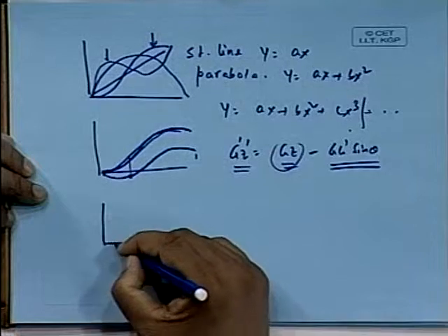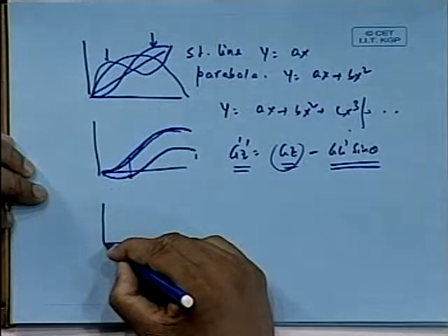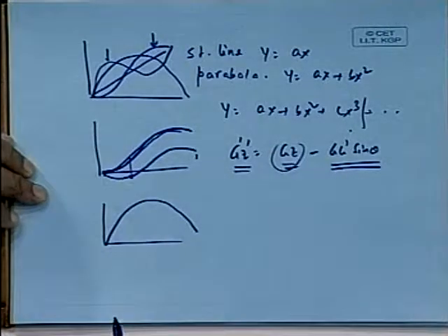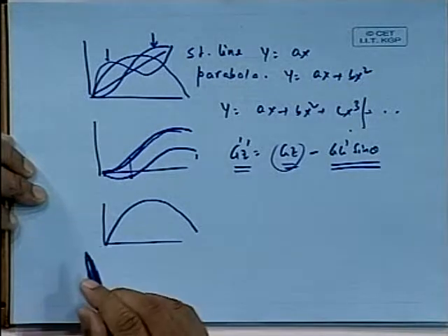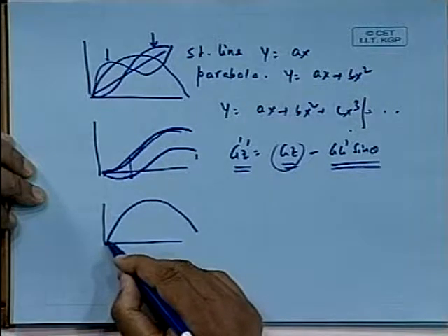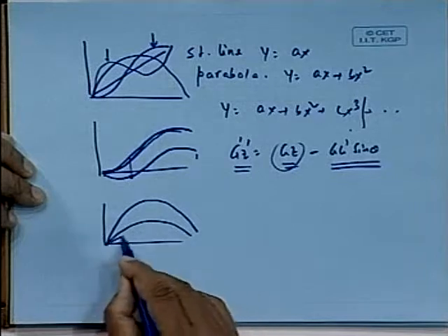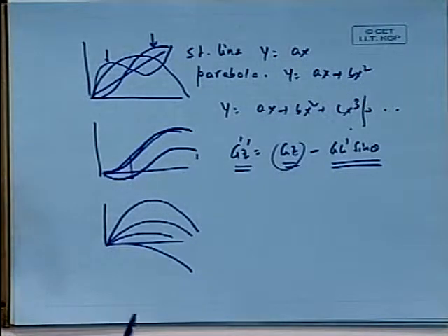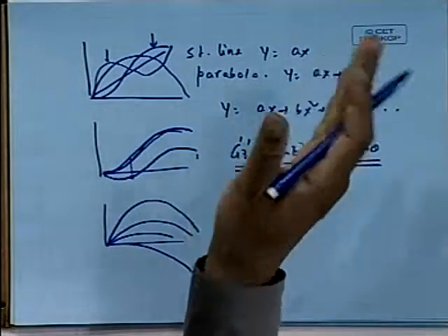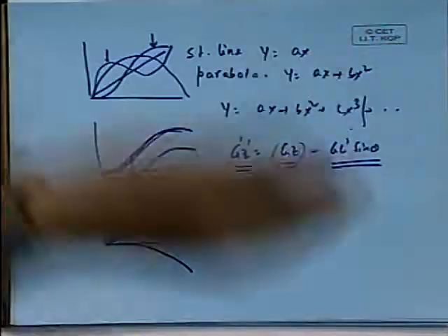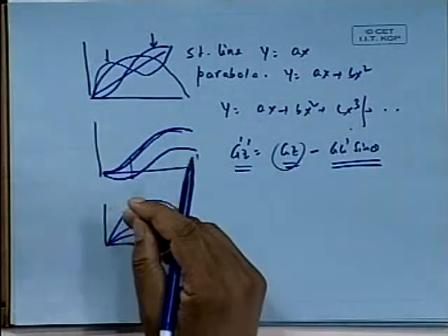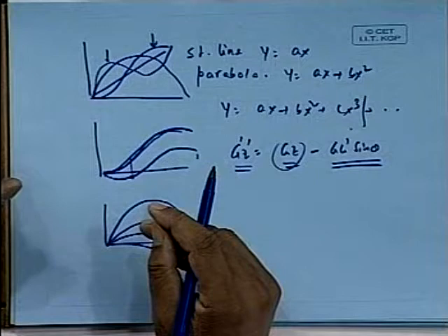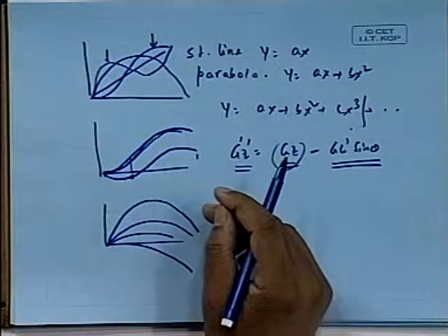Therefore if there is a ship, you consider a ship which has a GZ curve like that. This is not a good shape at all, because by some chance, if you have made GM negative, it will simply sink initially. That means if by some chance you raise the weight to a point where initially it is unstable, it will just turn slightly. This is what happens to a submarine, which we will discuss.